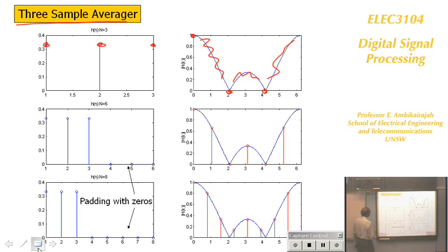So what I did then is I introduced 3 more zeros to it. I made the number of samples 6 there. And suddenly you see a value has been interpolated between those two by the discrete Fourier transform. You get another sample here, another one, another one. Now you can roughly join.